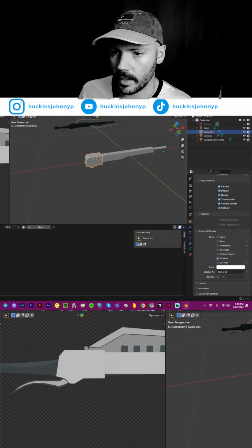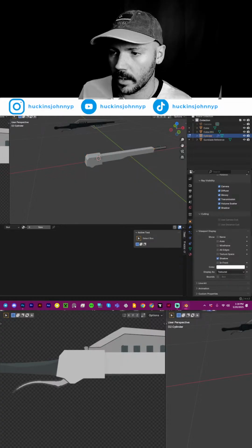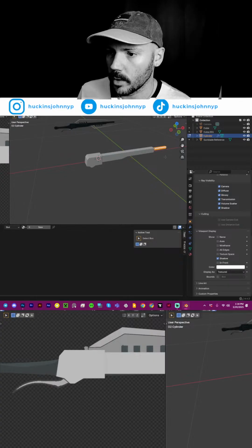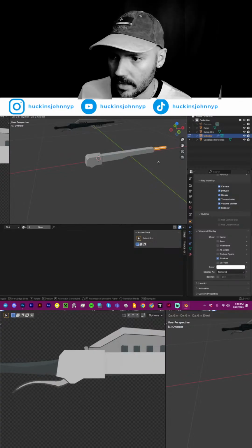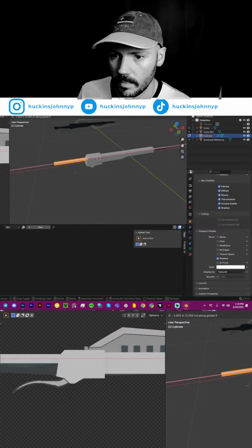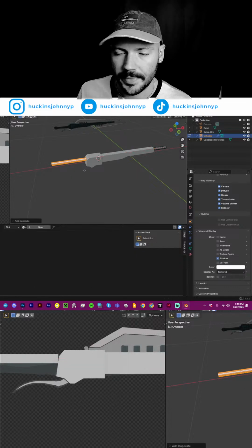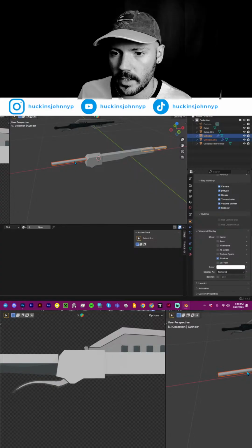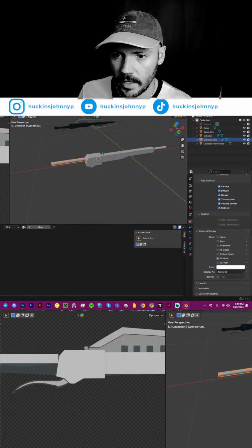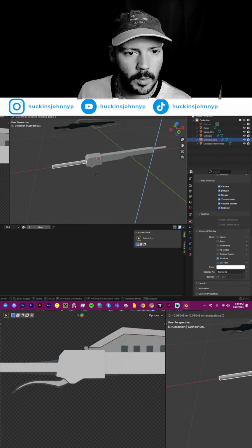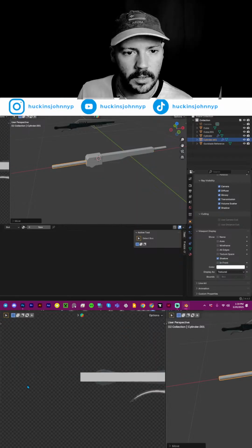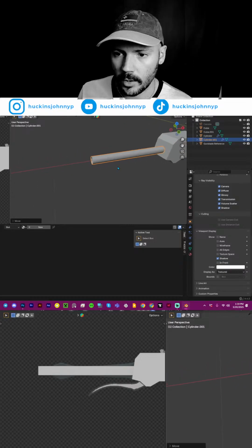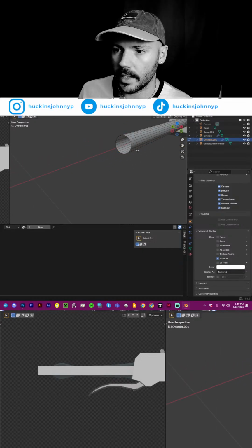So what I'm going to do is I'm going to go out of edit mode on that. I'm going to go edit mode on here. And I'm going to hit 3. And we're just going to grab this outside. We're going to go Shift D, X, bring it back to here. And then we're also going to go P, separate by selection, Tab, select this again, GZ. And we want this kind of dead center of our handle, right? Which is looking great. Now we can go back into edit mode.